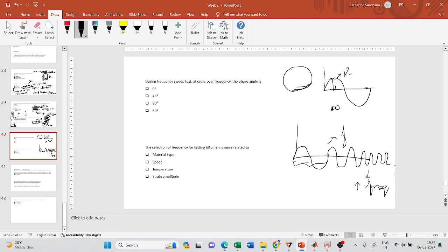So this is called a frequency sweep test, which means with the increase in time, I'm playing around with the frequency. The amplitude will remain the same in all the cases, and I'm changing the frequency with time. So had this completed in 1 second, this would have completed in 0.9 second, this in 0.8 second. This is called a frequency sweep experiment. I'm keeping the amplitude as a constant and I'm varying the frequency with time.